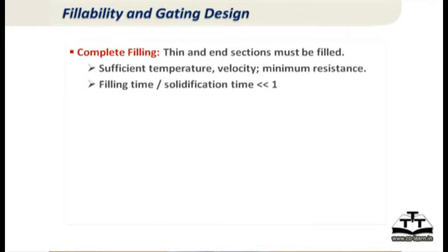So, 3 last final rules of gating design. For complete filling, we have to ensure that the filling time is much smaller compared to solidification time. This is especially important in thin wall castings, where solidification time can also be very short. So in thin wall castings, you have to really fill fast so that your filling time is lower than your solidification time, otherwise you have unfilling problems.